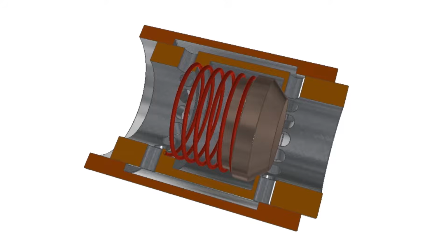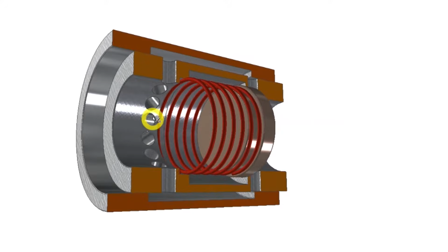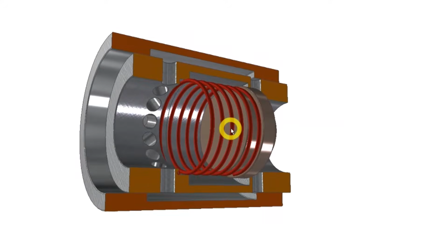This is a more advanced type of choke valve. We call it a choke valve with an open return. It is used in instances when you want to control the liquid flow and component speed in one direction, but where max flow is required in the other direction. So if we have liquid entering on this side of the valve, the liquid will pressurize this valve seat and push it against the valve body.